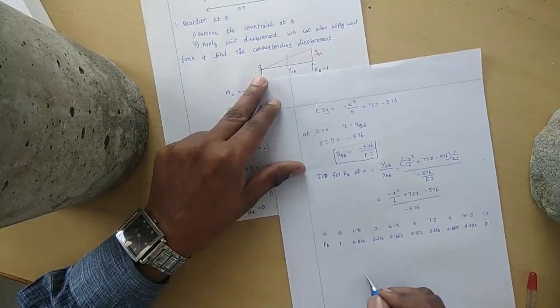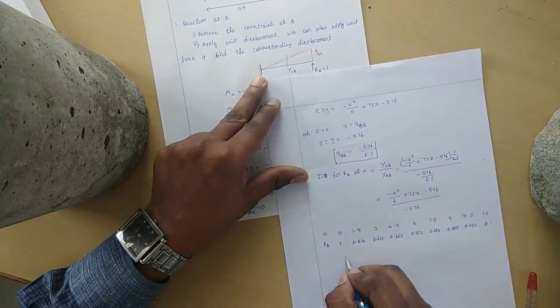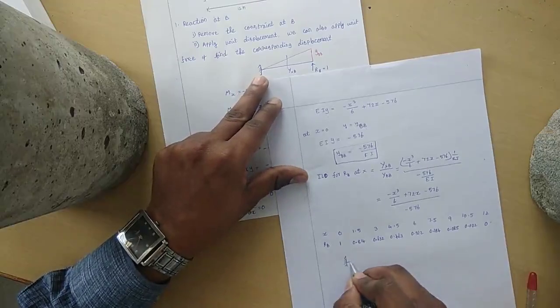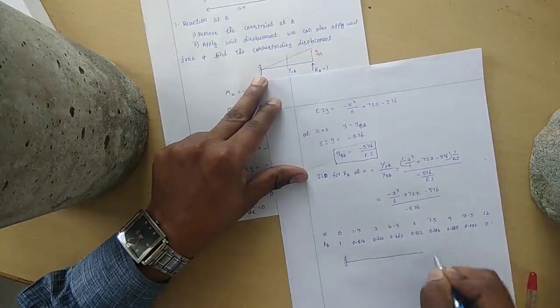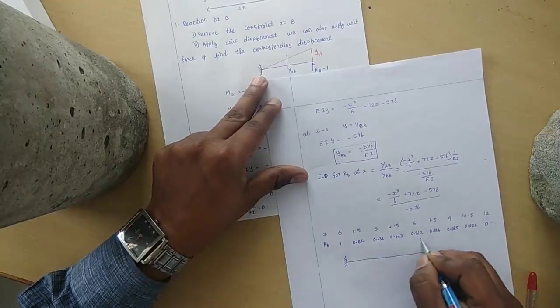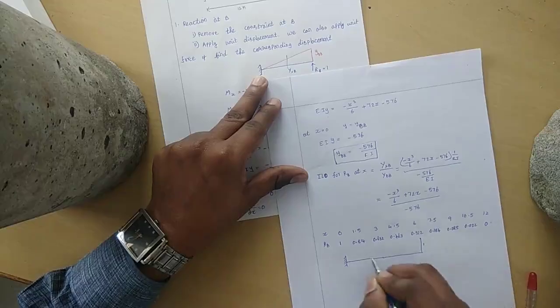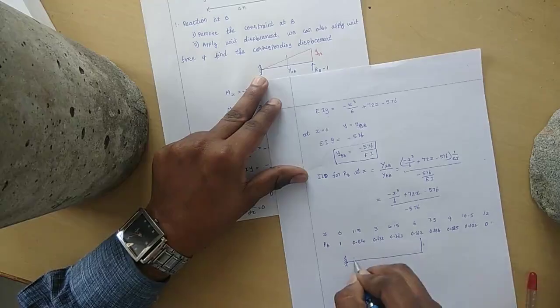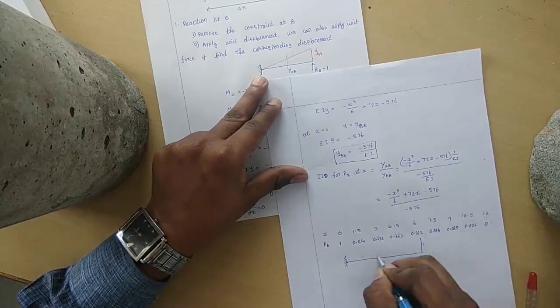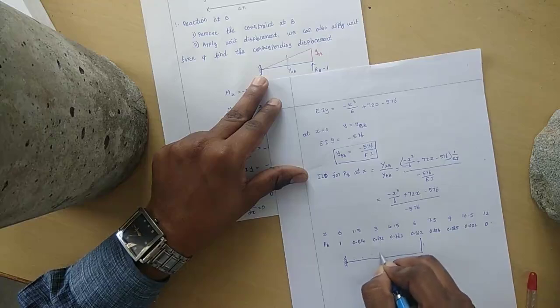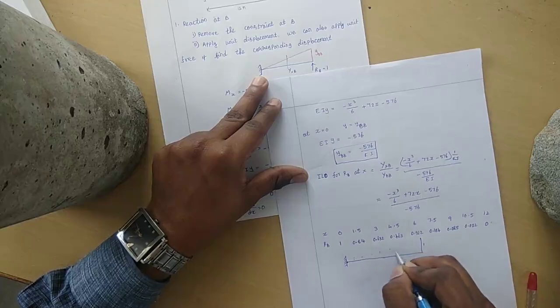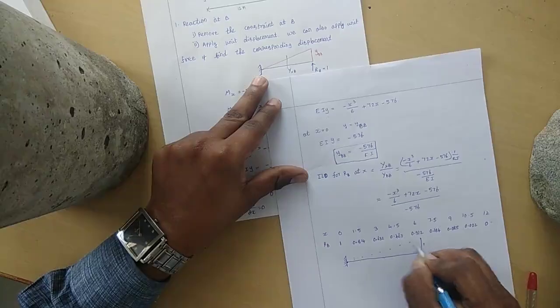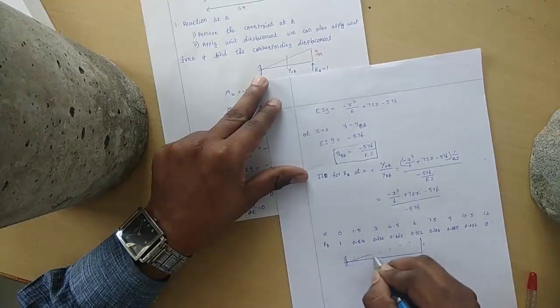Next, we are going to draw the influence line diagram for the given problem. I am going to mark it here. This is the 12th meter, so the value will be 1. Next, I am marking 0 here. Next, 0.022 will be here, which is very small, and 0.085 like this. Again 0.184, 0.312, 0.463, 0.632, 0.814. If you join them, the curve will be like this.